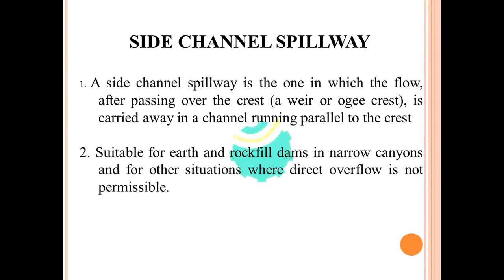So the water is carried away from the running channel to another channel. It is suitable for earth and rock fill dams in narrow canyons and for other situations where direct overflow is not permissible. Mostly in earth dams, we provide side channel spillways. Ogee is constructed mostly on the dam itself, but the side channel is constructed in a separate place.